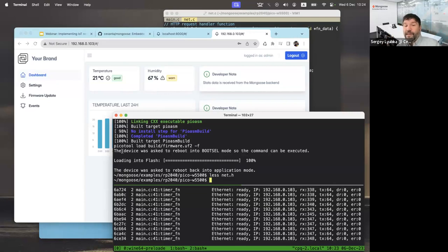It's really easy to denial-of-service an embedded device, because it has so little resources. So it's not recommended, even if you run the web server on your local network. You probably don't want to expose it to the public.